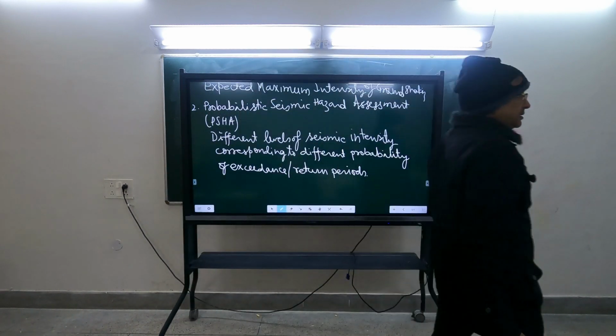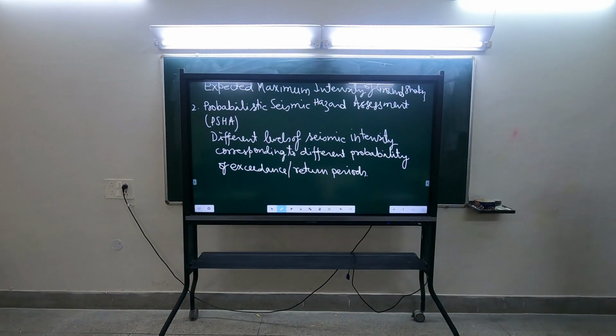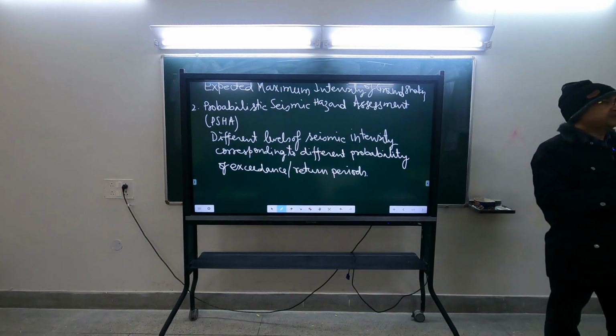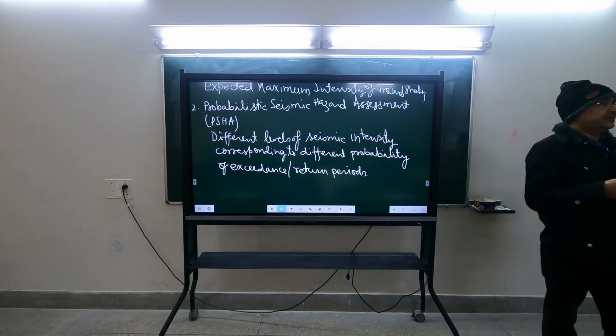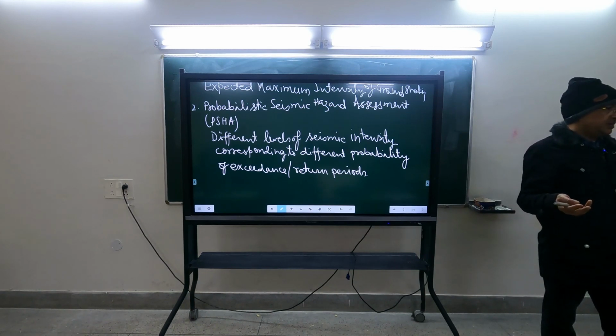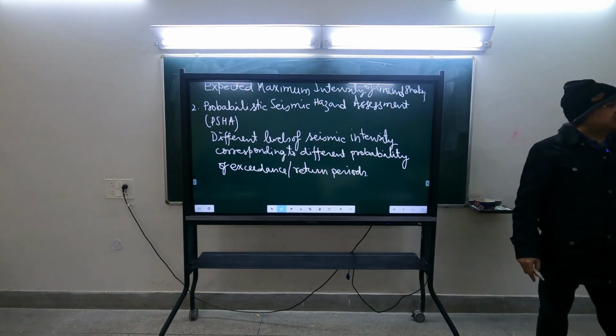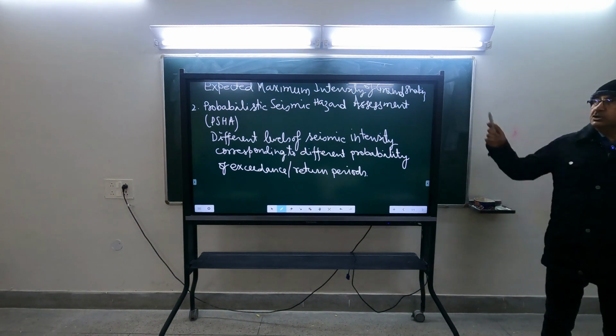In DSHA, there is no concept of probability of exceedance or return period. In PSHA, different return periods will lead to different response spectra, different PGA, different intensity measures. Okay, so this is the difference.